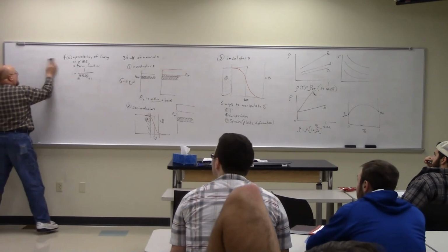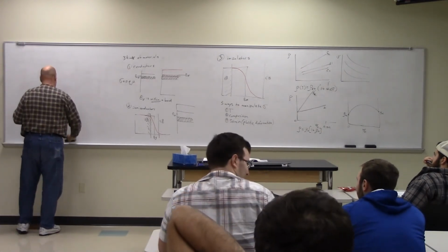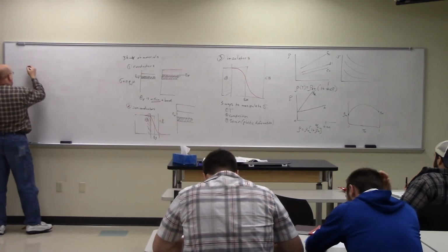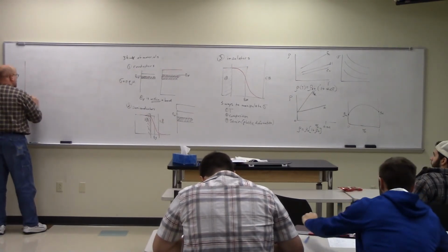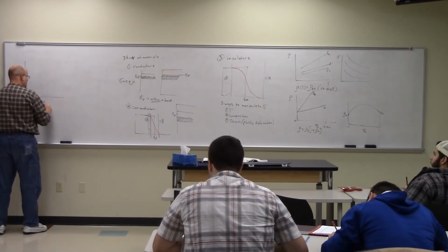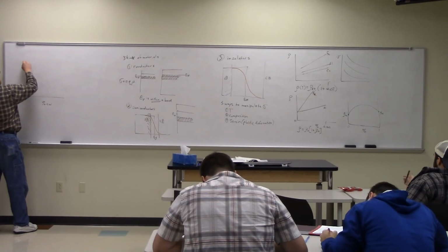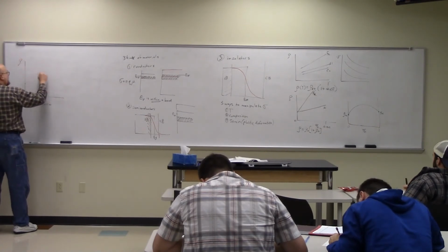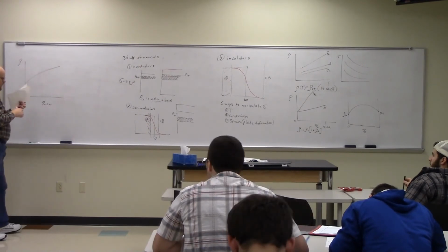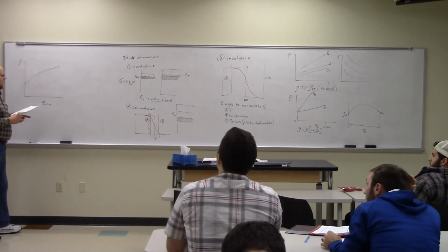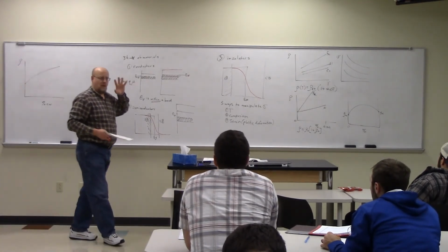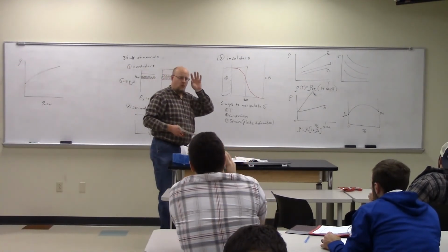it's a similar behavior. As I strain it, the resistivity goes up. So this is percent cold work, and this is the resistivity, and again it has some kind of behavior like this. There I don't really have a good strong relationship, but you get the idea. Because here, again, dislocations and lattice strain are all going to inhibit an electron's ability to move uniformly through the lattice.